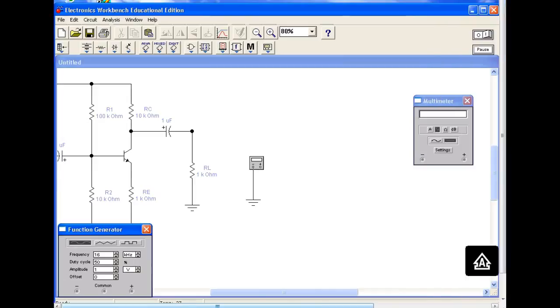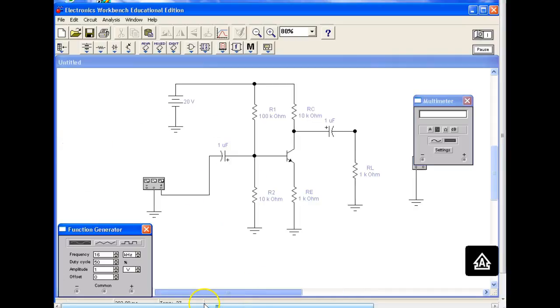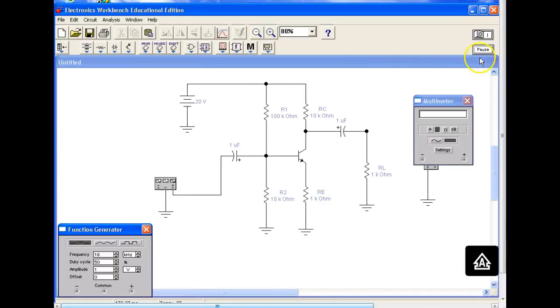Oh, there's another place. There it is right there. So we'll turn the simulation on, and it will just come back and measure. So when we measure voltage on the base, if this thing does according to our calculations, here we should measure 2 volts. Here we should measure 1.3 volts. Here we should measure, what was that?